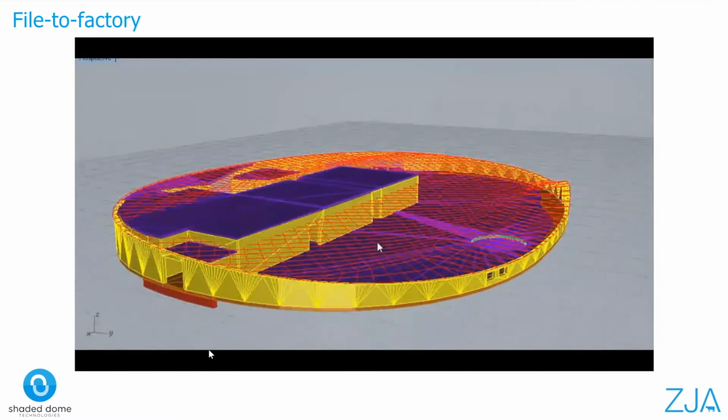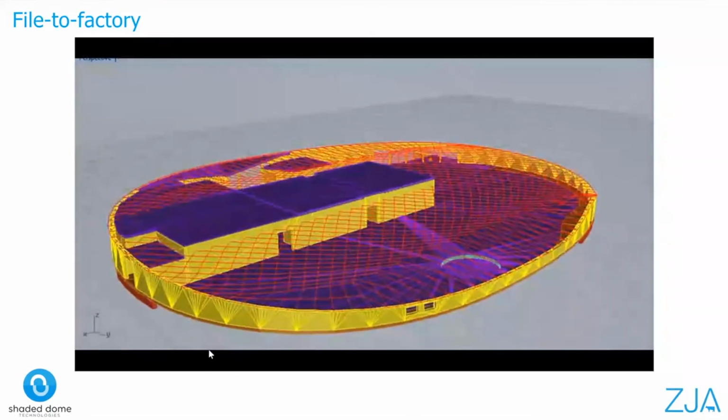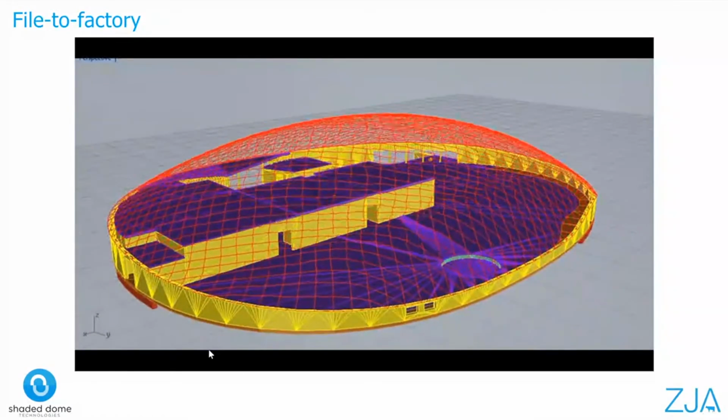After this verification, the latest adjustments were then introduced to our parametric model. Our algorithm then generates relevant files for the components, be it the dome, the cable net, the struts in between, and finally the shade and the suspension cables, which are necessary for manufacturing and assembly of the building.